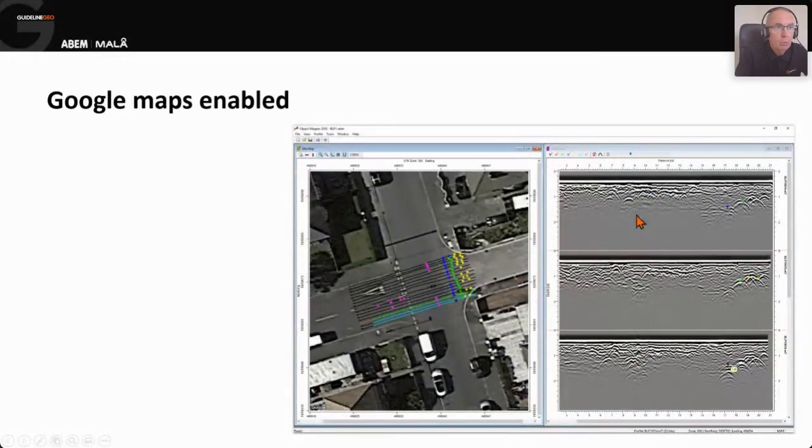The green is the top profile, and the 2 blues are the ones underneath sequentially. If I wish, I can just click on any of the profile lines in the sitemap, and you'll see the 3 lines appear on the right-hand side: the one that you selected and the 2 after it. Like I say, you can increase or decrease those numbers if you wish. I tend to have 3, maybe 4.